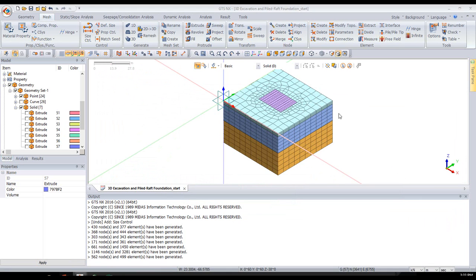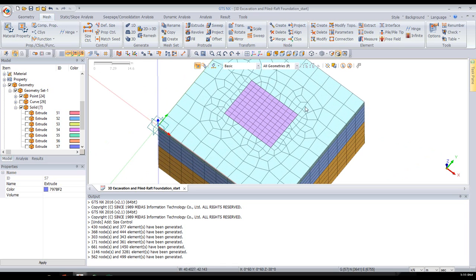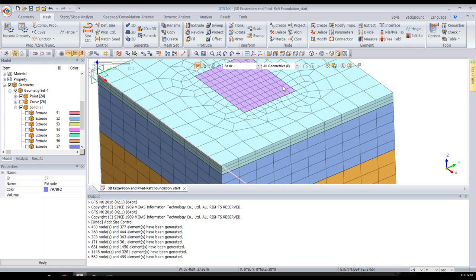Okay, so we're done with the initial meshing. We can actually check how well these layers were connected. Well, one is to give it a visual inspection, and we can clearly see there is a gradual change in size from the outer boundary to the inner boundary of our soil. And you can actually see the connections line up. You can see the squares of the blue lining up around the same size of the smaller squares in purple. So a quick visual inspection lets us know that it looks connected.